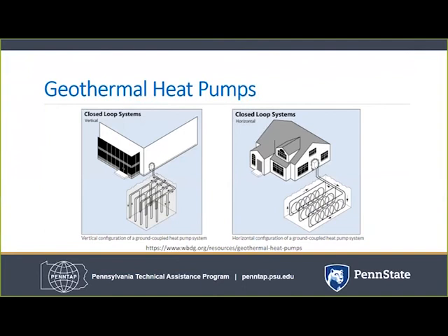In hot weather, the fluid will be colder than the air and can provide cooling to the building. In cold weather, the fluid will be warmer than the air and can provide heat to the building. Two styles of construction are shown in the slide. One uses deeper vertical loops, while the other uses horizontal loops.